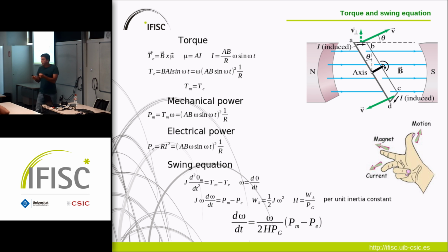Essentially, if you want the voltage fixed and the frequency fixed, the machine has to produce a mechanical torque that has to be equal to the electric torque, the torque provoked by the electricity. And that's the issue, essentially. A power plant generates a mechanical torque to compensate for the electrical torque in the coils of the generator. And that's everything that I'll talk about today, essentially.